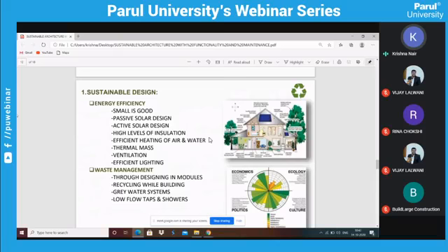So what is passive sustainable design? Basically, it's all about using and controlling the climatic conditions, or say the contextual climatic conditions, through various elements of the building to increase the building sustainability. Here the building design helps in using the elements of climate like wind, decreasing the active and sustainable design needs. So what are the different elements of climate which generally affect the building? The major ones are wind, water and sun.